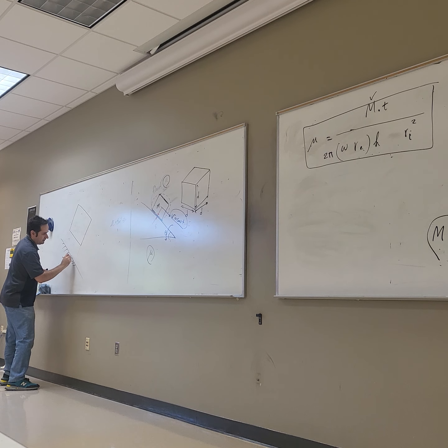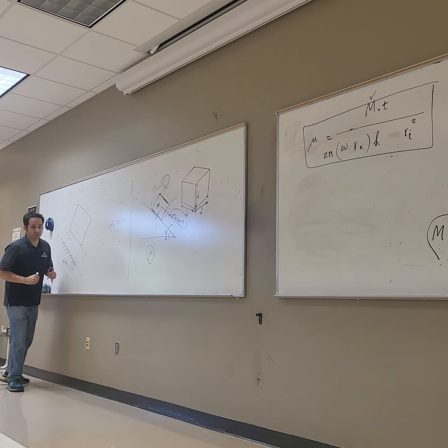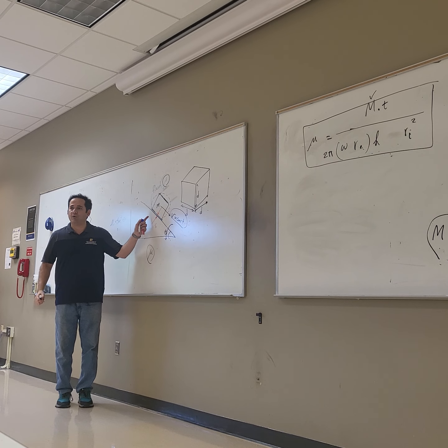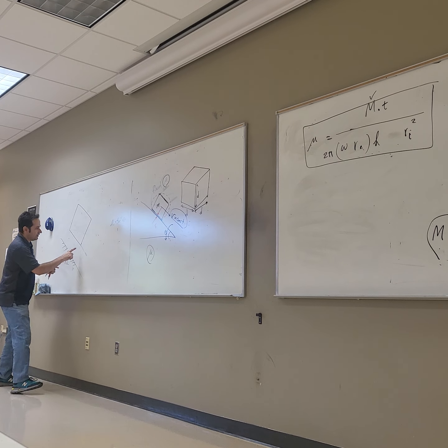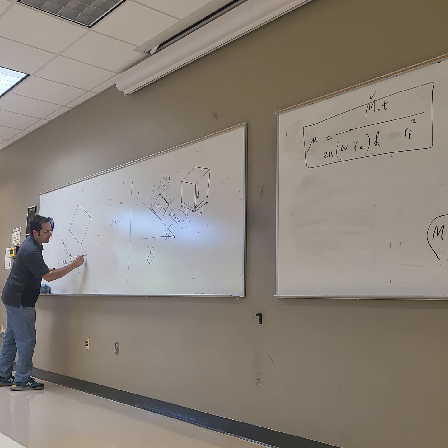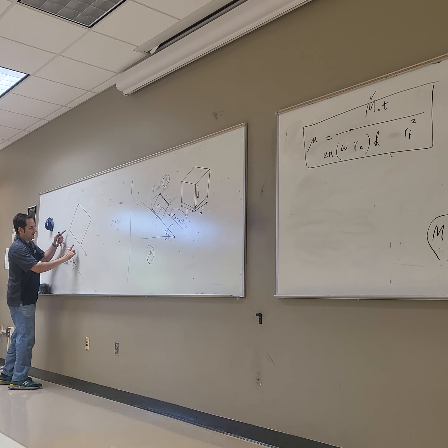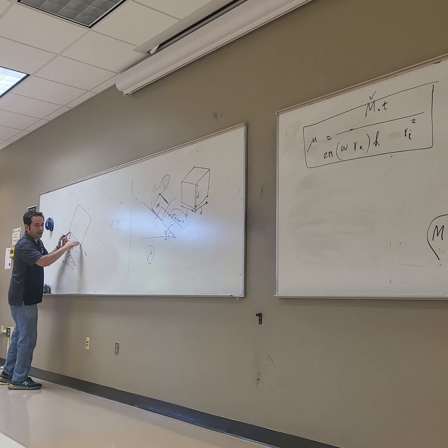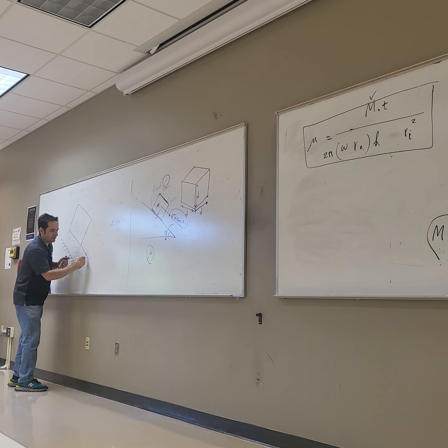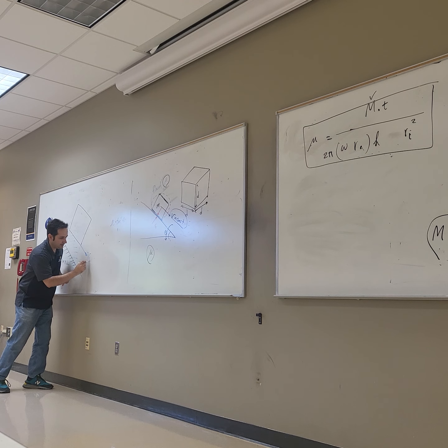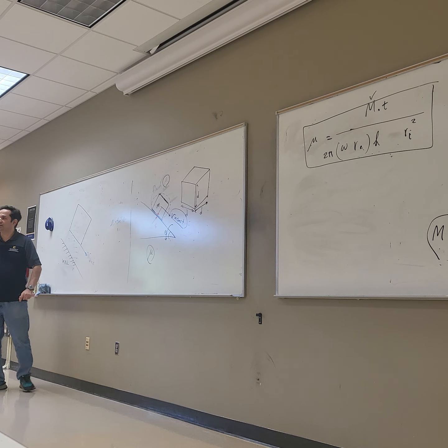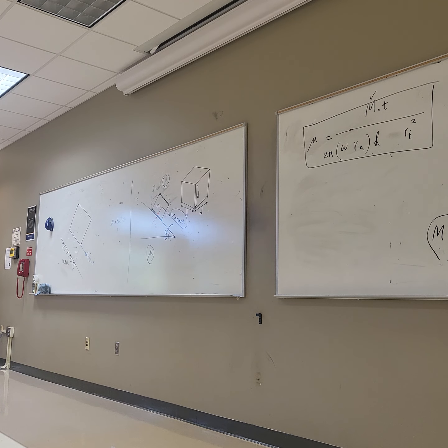Right? So you have fluid going fast here, and then the velocity. What's the velocity of fluid here? What's the velocity of the lubrication at the wall? 0. Just 0. What's the velocity at the interface between the block and the fluid? So that's a fluid, right? What's the velocity here at the interface of block and fluid? V constant. V of the block. And we know that the V of the block is constant. Why?